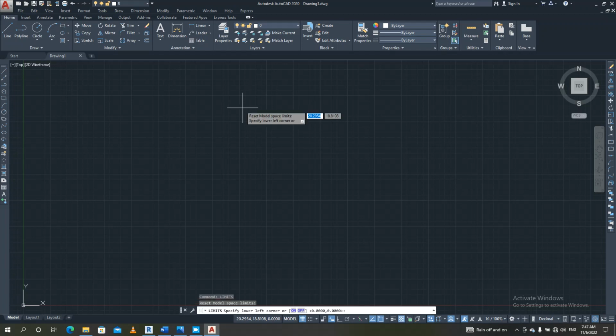Once you press enter button, a dialog will show demanding for origin of X and Y axis. So input the first origin as 0 and lock it by pressing comma button. It has locked. Input the origin of the second distance, 0 also, and press enter button.